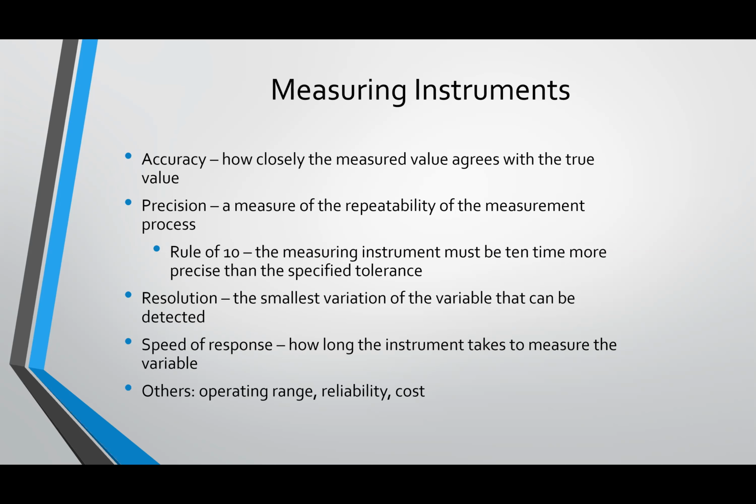So if the resolution of the device is to the thousandth, that means that the marks on the device or the capabilities of the device are to the thousandths. If you think of a basic steel rule that's in inches, you might get down to an eighth of an inch or a 16th of an inch. That's the resolution of the device itself.